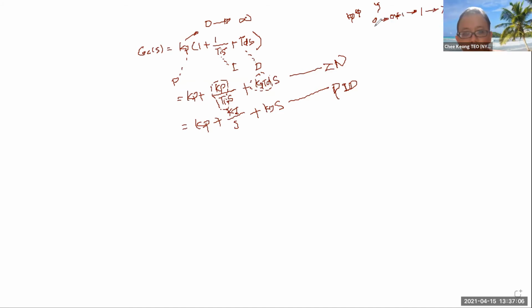So your zeta will run through these ranges. This part at 0 is of course oscillatory, and between 0 and 1 it is slightly oscillatory because it's underdamped. Now this is of course stable, because it is greater than 1, let's say 10. So if you change your gain by moving it higher and higher, KP increases.